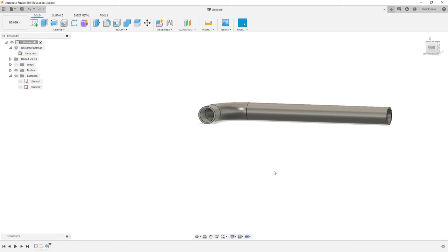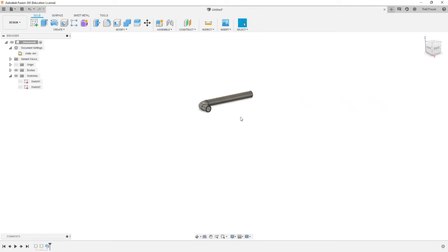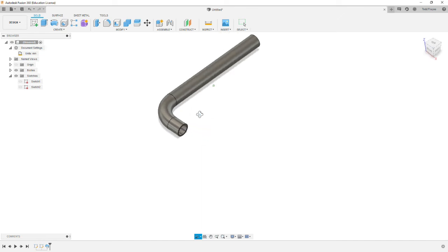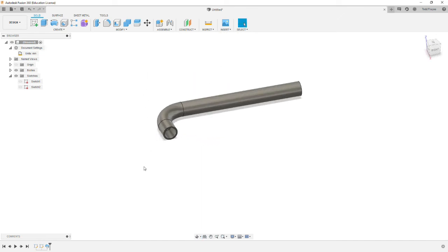Now there's an alternative way to approach this. You could have made it solid and used another command called shell, and it would give you the wall thickness. And that works well if you're doing very complex bends and you're doing a lot of them, and you want to, say, make a weldment and have all consistent wall thicknesses. Okay, there you go. That concludes the TCOSE-13 CAD tutorial.